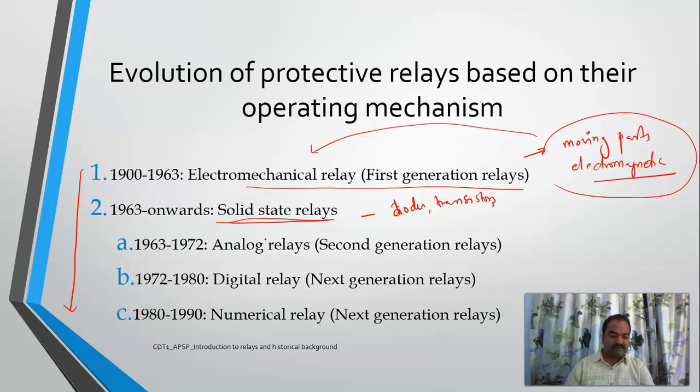The advancement is the PC based relays. Now we have got intelligent electronic devices, IED, that I'll show you in the next slide. So the world is moving ahead with advanced protections, which you call digital or numerical relays. Maybe in the future we'll be seeing completely IEDs, intelligent electronic devices, for sensing of the faults. The electromechanical relays are on the verge of extinction nowadays. But still there are some applications where you can see electromechanical relays.